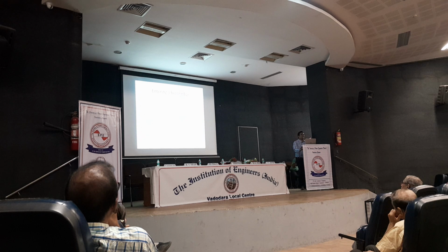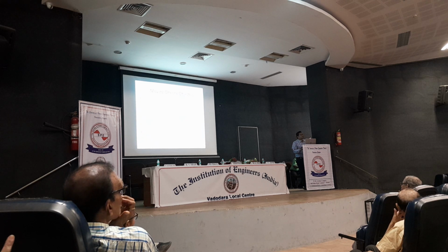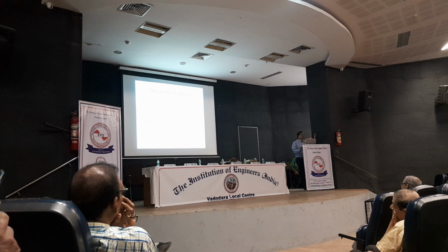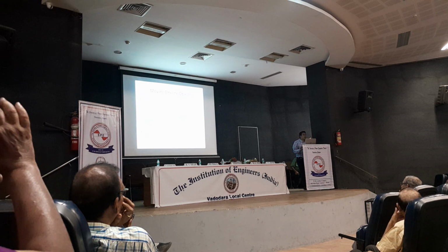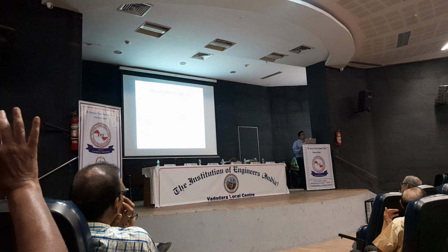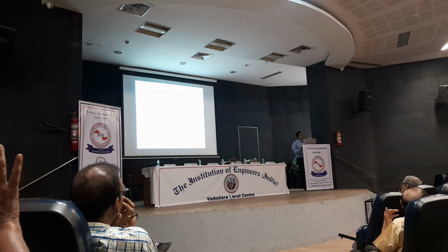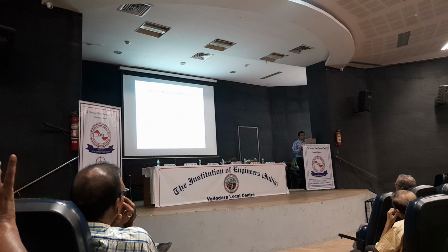Now when you select the second bus from the draw option, the numbering will come automatically. Similarly, you have to enter the bus voltage. Once you enter the bus voltage, the task is done. Then you have to select the load for that particular bus.